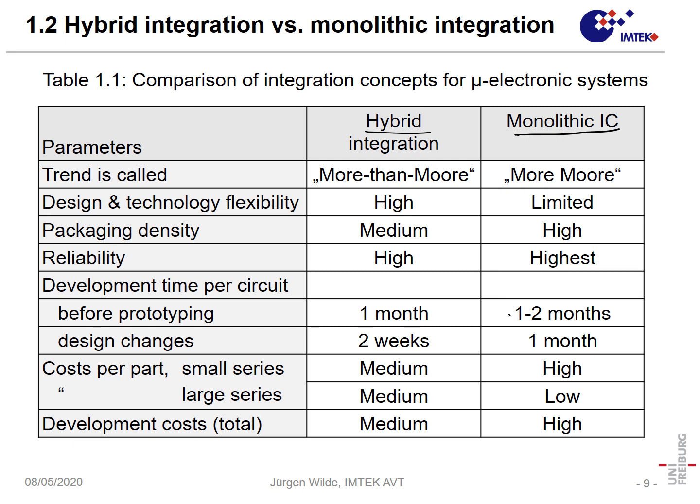Design changes in hybrid integration can often be accomplished quite fast. On the other hand, if you have an IC which you create on wafer, you must have a proper time slot in the wafer fab, and that can take months until you have a new wafer, which requires many masks. In that case, you make a completely new wafer. When you do hybrid integration, maybe you only change some parts of your circuitry.